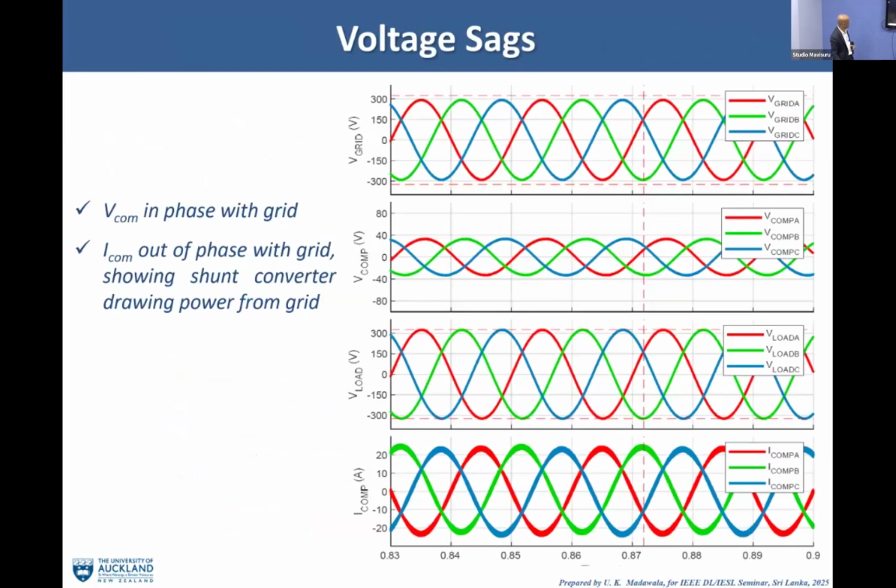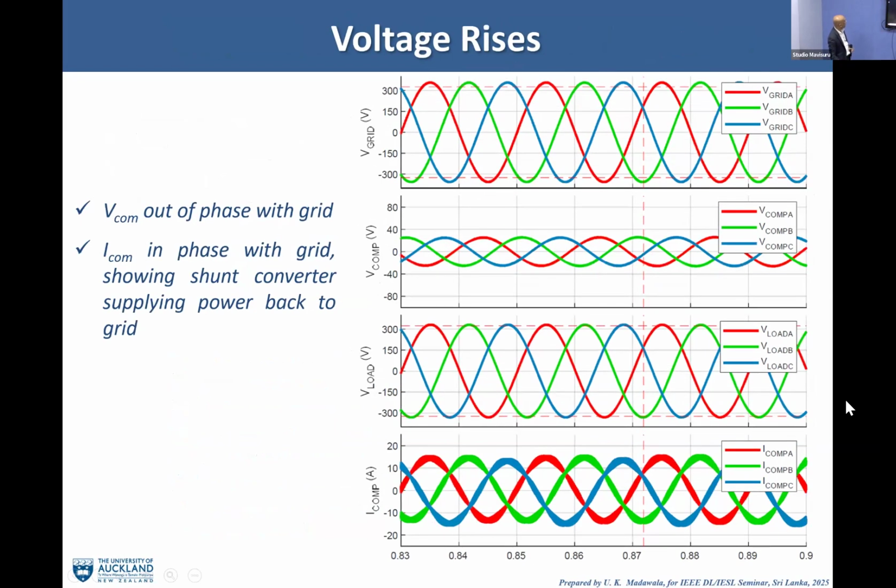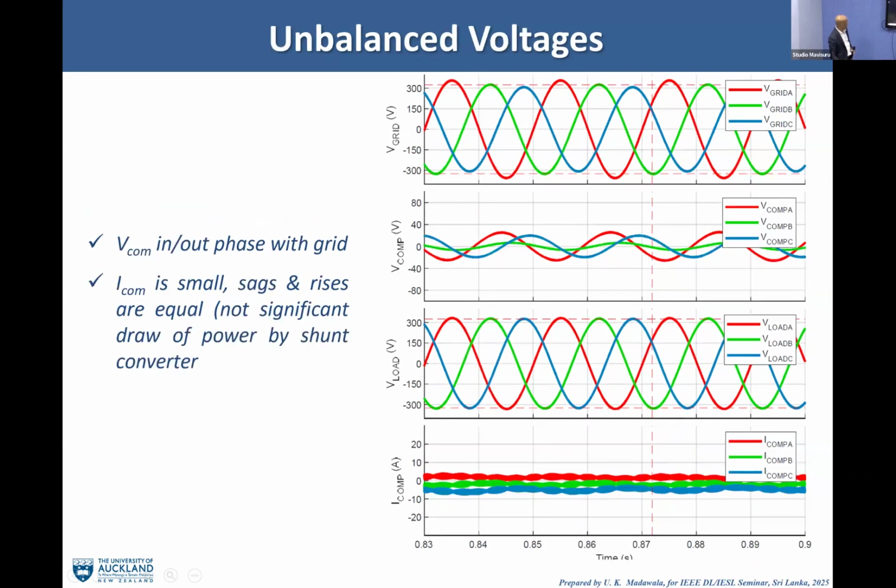Since we built and tested the system, there you can see how the grid voltage is. As you can see, these are the unbalanced conditions. The grid can still be balanced because we are injecting voltages into the grid. There you can see the voltage rises, higher than what we need. Normally we use what you call the online tap changers, but here you can see all the load voltages are not balanced. Some of the voltages are unbalanced, so we can balance them too.